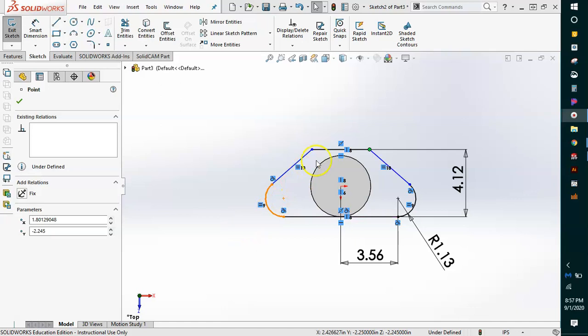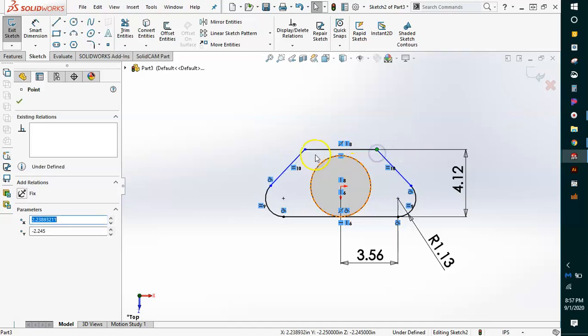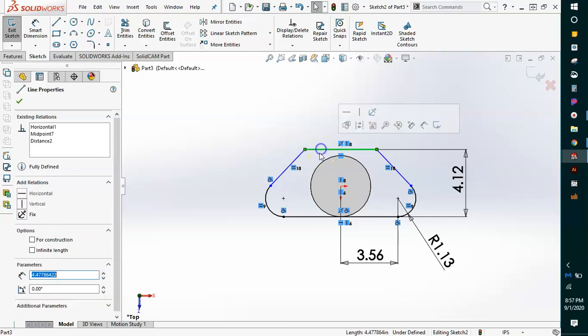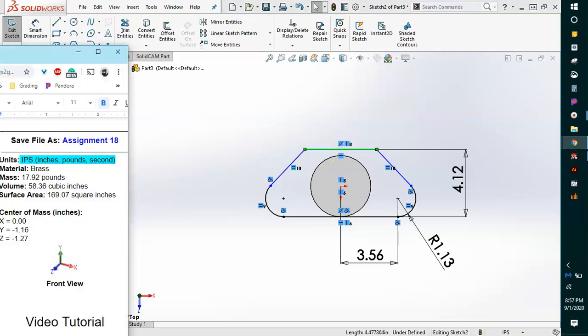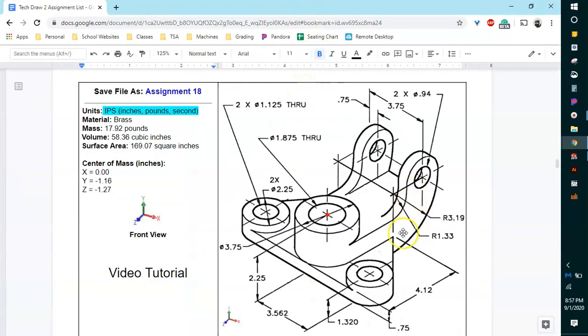And we still have 2 blue angled lines, so if you click and hold on a dot, so you had to get off of your dimension tool. I hit escape, sorry about that. If you click and hold on one of these blue dots, you can see it still moves in or out. So what's going to define this is the length of that line up here. Now, that length of that line is actually going to be the same measurement as the width of this inside piece.